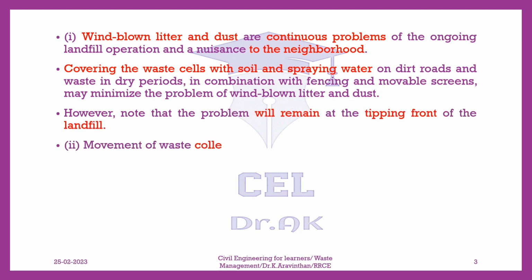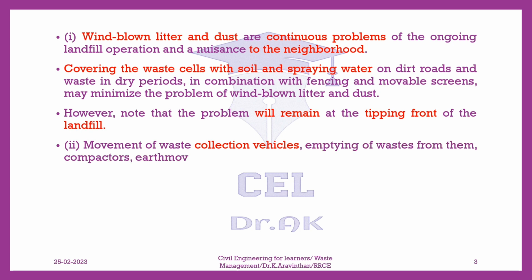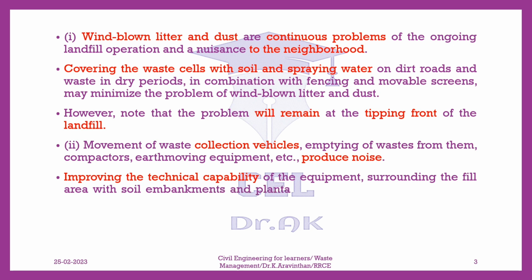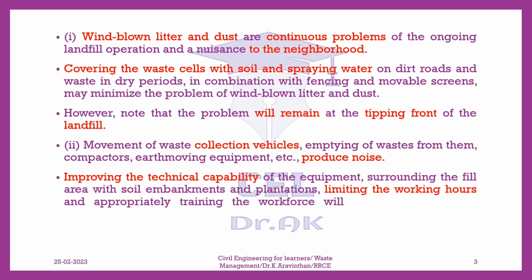2. Movement of waste collection vehicles, emptying of wastes from them, compactors, earth-moving equipment, etc., produce noise. Improving the technical capability of the equipment, surrounding the fill area with soil embankments and plantations, limiting the working hours, and appropriately training the workforce will help minimize noise pollution.